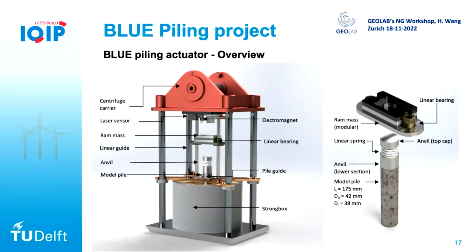Another good thing is we can decrease the noise during installation, because offshore you have a lot of creatures around the pile. If you use a traditional hammer, normally you will see a lot of fish floating around the pile after installation, because that really kills the fish. So we want to improve that also.